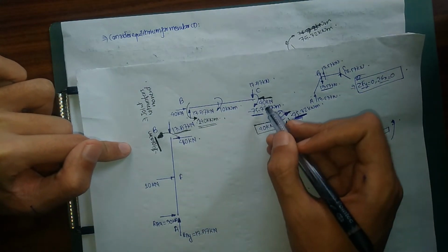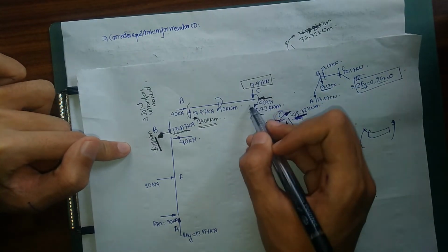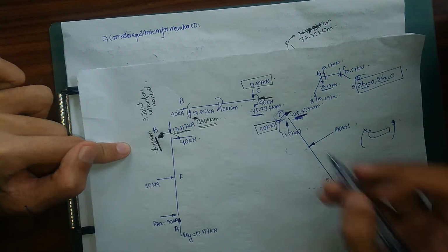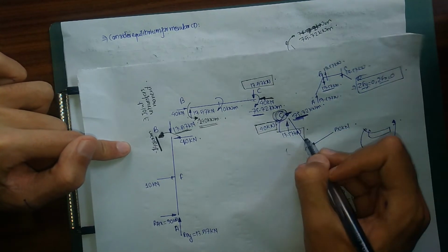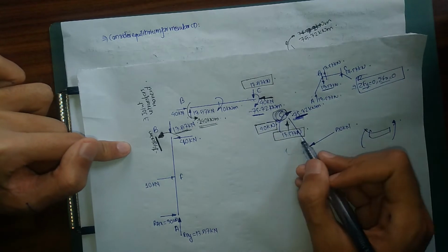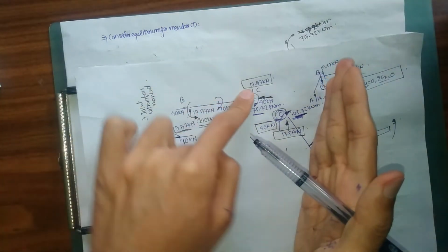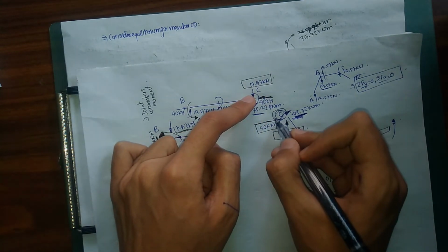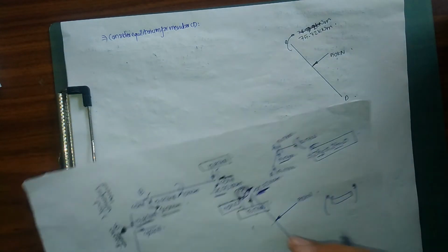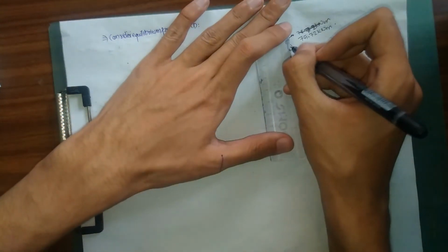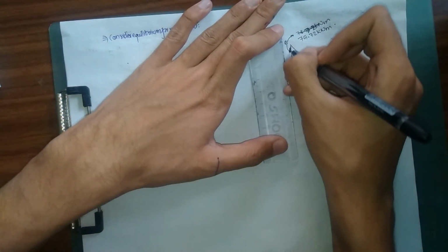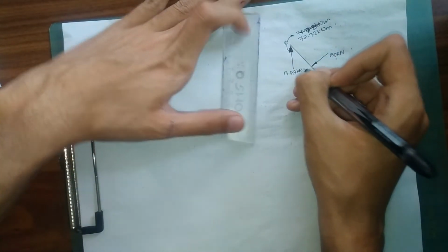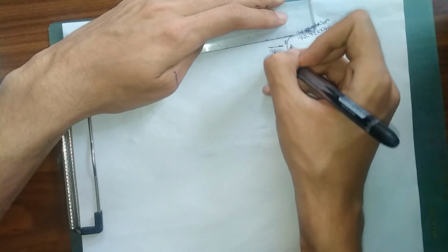Similarly, there was a force of 13.57 kilonewton acting downward at my joint C for my member BC. So for my member CD at joint C, 13.57 kilonewton must act upward in order to maintain equilibrium. They must act in opposite directions in order to maintain equilibrium. So I need to put that on as well: 13.57 kilonewton acting upward, and my force of 40 kilonewton acting at right.